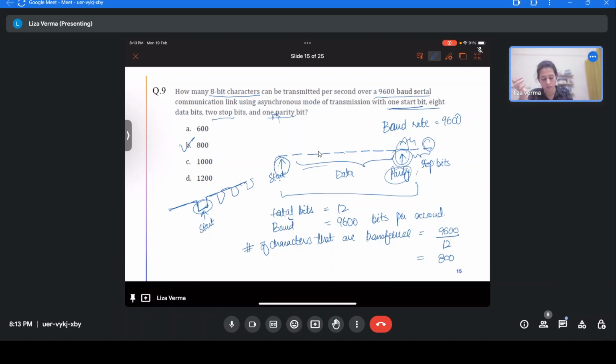Then whatever is the stop bit, stop bits can be any combination of bits, 0, 1, whatever. Like there are 2 bits, so you can have 4 combinations of stop bits. There's a convention chosen for the serial communication.